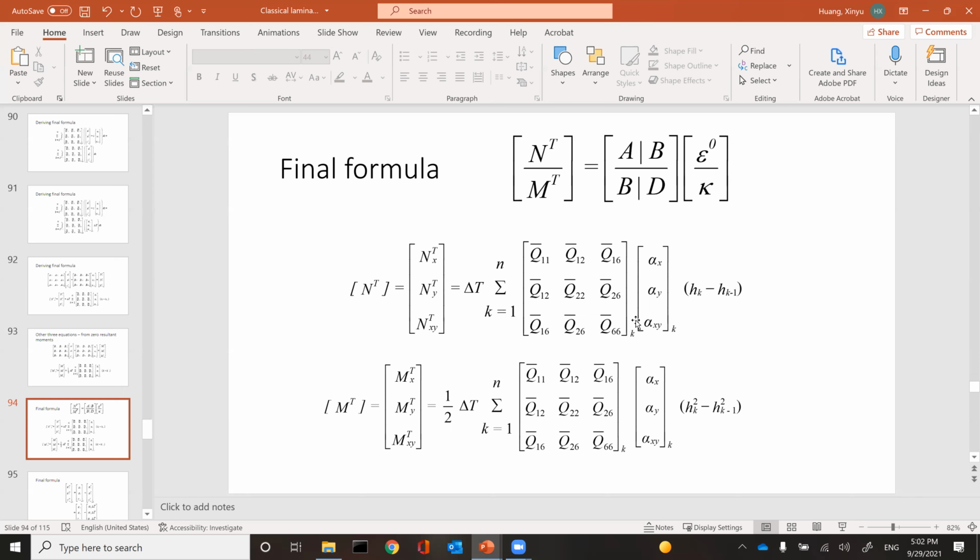Then we'll start by calculating a few standard cases. We'll check notes. You write your code, and I have my code. I calculate a set of laminates with every result in every step, and you check against your code. So we benchmark against each other, and then we'll do numerical experiments with your code: different layups, symmetric, anti-symmetric, quasi-isotropic, cross-ply, all those things. We'll see what kind of ABD they come out with, what the thermal effect is, and how they will work.